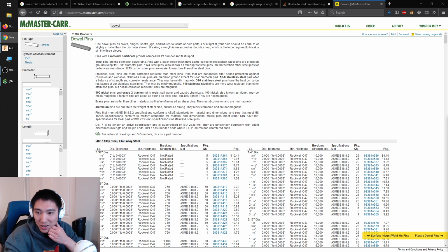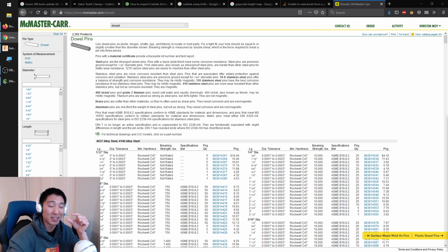The shank of the tool and the cutting diameter of the tool can be different. Yes, collets have many sizes within their type. If you want to keep the same collet, get a tool with the diameter you need. Collets have a crush range. You can't take a 1/4 inch collet and put in a 1/8 inch tool.